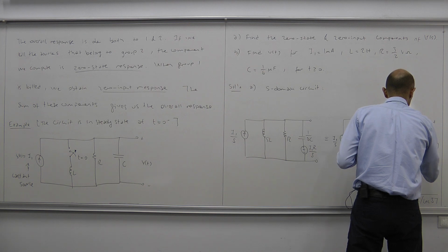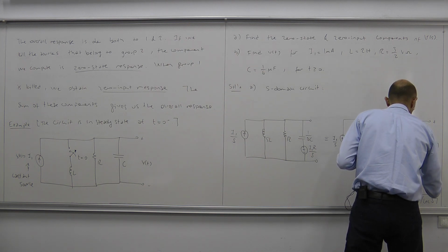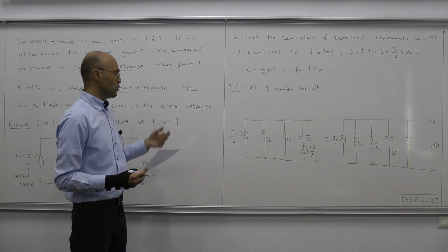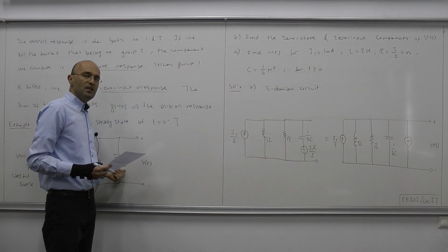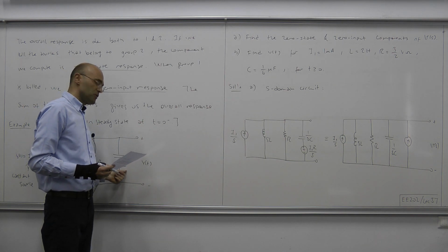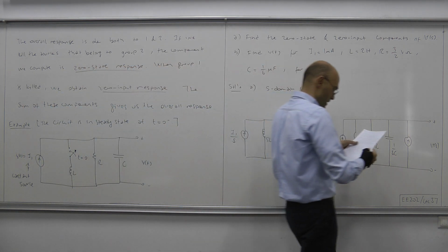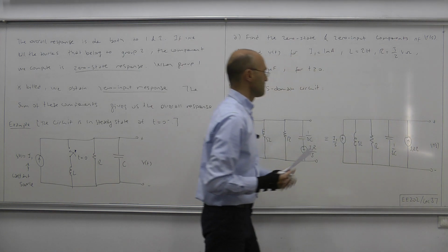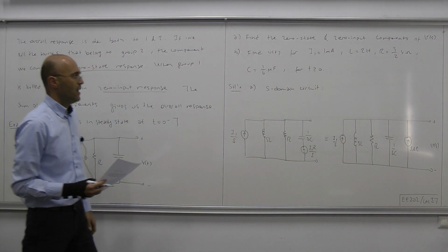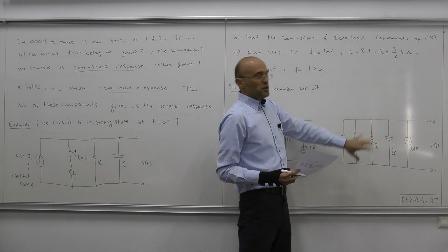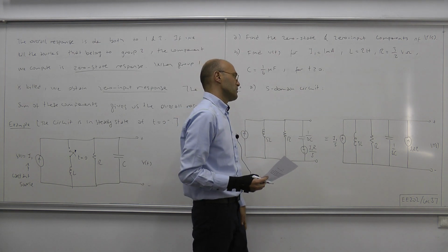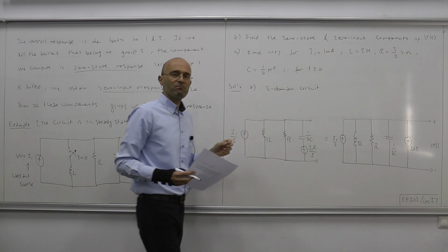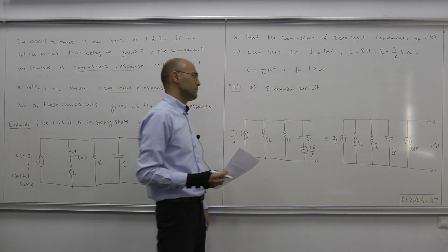And that current source has current that equals capacitance times the initial voltage, CV0. Initial voltage is I1 times R. Therefore, here we have I1R times C. Okay. Now all the sources are current sources in our circuit, or all the inputs are current sources. And we can easily classify those inputs.